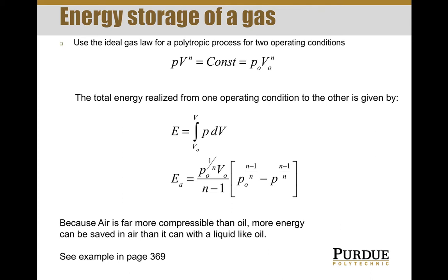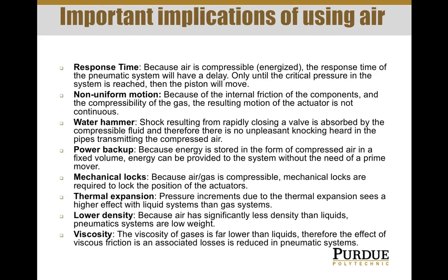The difference is 1 to 3%. So basically, of 100% of energy you can store with compressed air, only 3% can be stored with that oil due to compressibility. So gas is very good, air is very good at storing energy. You can use it to save some energy.